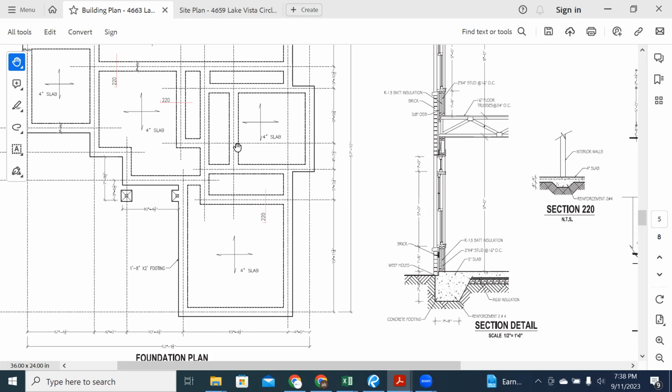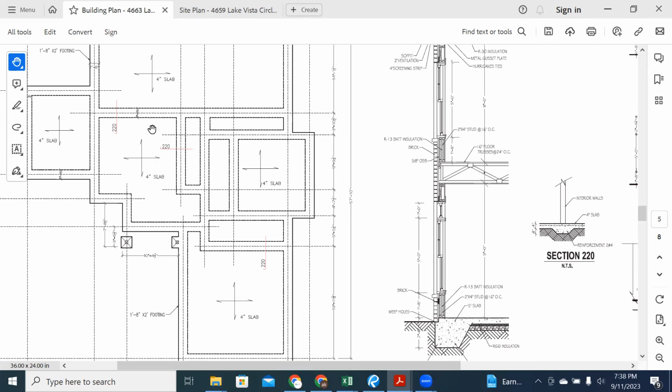So when you saw the video and I'm walking across showing you, you saw all the rebar laying on top of the plastic. After we get that down, then we have a wire mesh, which is also in the video. And then we put that mesh all over the slab, all over the plastic. We cover all of that. That's to help us with the concrete as well, to bind it. So we put all that there, and then we call for inspection.